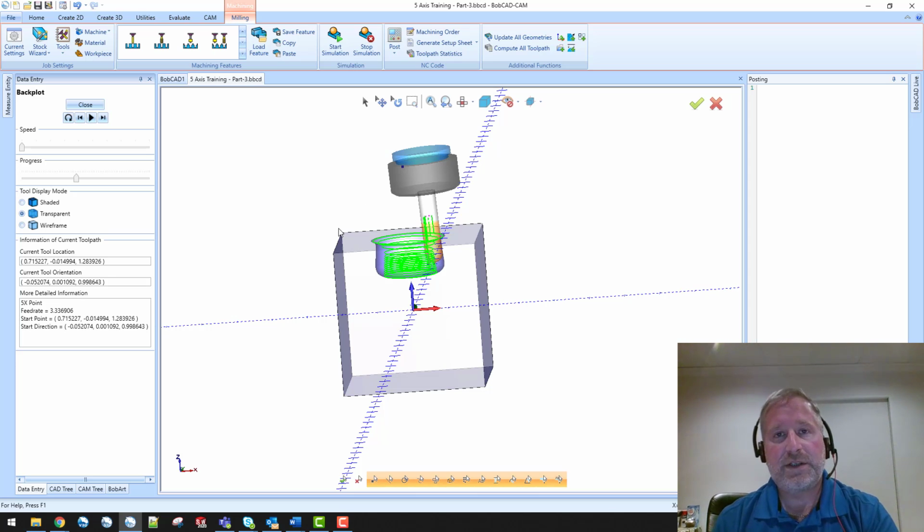So again, this is something that I use commonly for porting. There are some other methods that we can use as well, using curves and things like that, and we'll get into those in another video. But hopefully this shows you a little bit of how tilted relative to cutting direction and tilted through a point can be used, and what they actually do, and gives you a better idea so that when you're trying to apply those strategies to your parts, you'll be able to have more success.